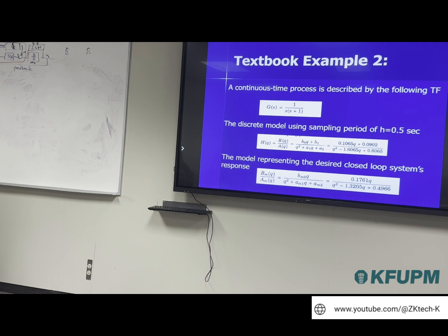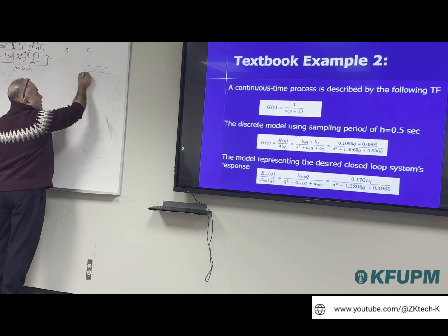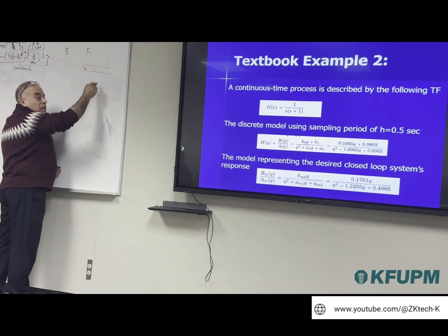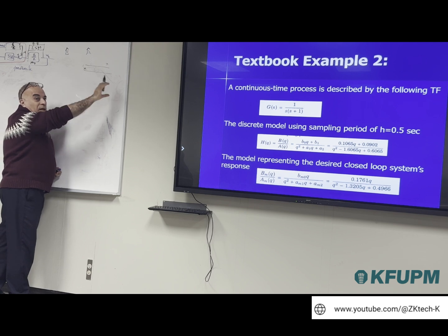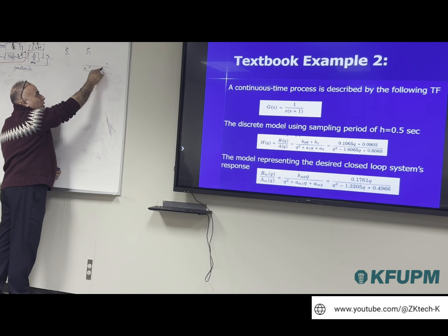For example, in Aramco they have what we call data compression. They have some software they run, but they don't take all the points. So what they do, they put an upper limit and a lower limit like this. So if they get the value here, unless the next value is out, they will keep the same value. They will not change it. So you see here the values like this. They are all this one.